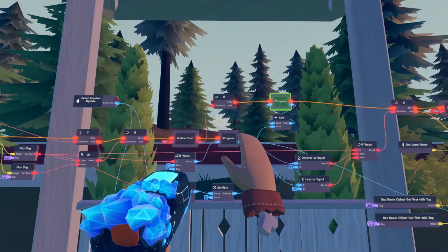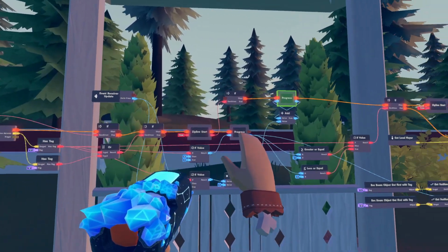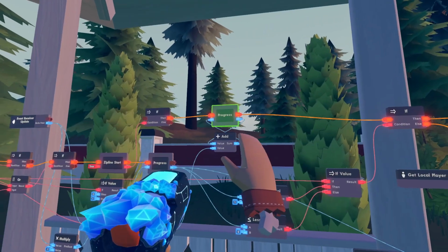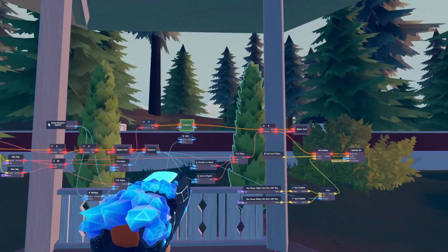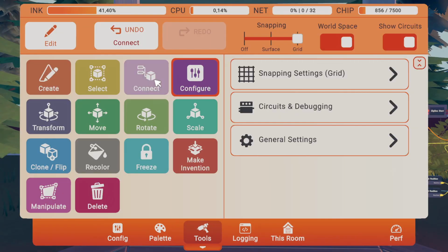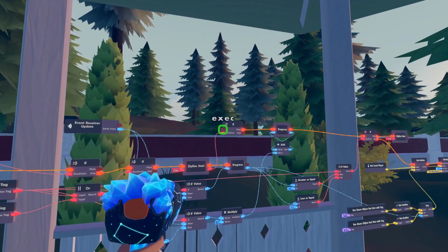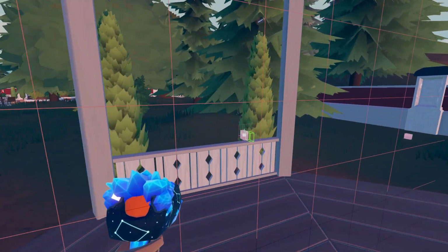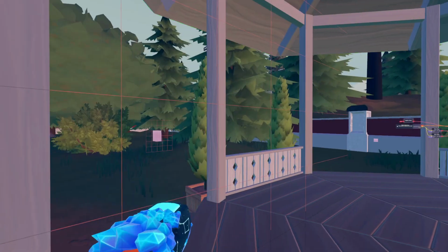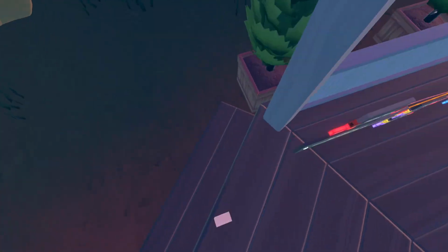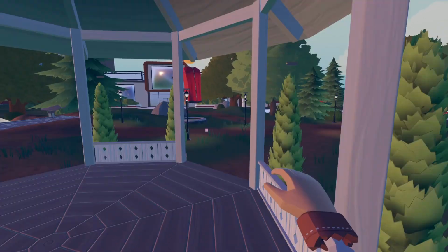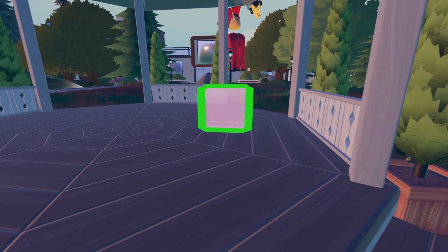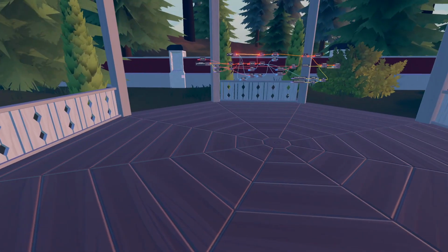So now the different variables that I have now have the same name. So all the bool variables have zipline start, and all the float variables are called progress. Now you can then wire the update into the event receiver. If you now space out the two interaction volumes you have, and I then click one of them, I will go from point A to point B, just like a zipline. Now, as you can see, I'm being set above the interaction volume.